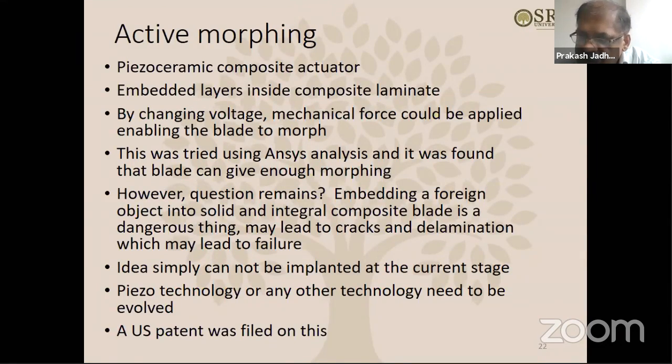When we hand lay up the carbon fiber epoxy prepreg layers, at that time we can incorporate those piezoceramic layers, and that's how we embedded those layers inside the composite laminate.